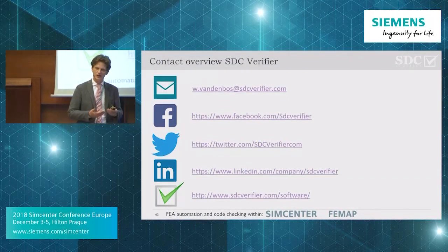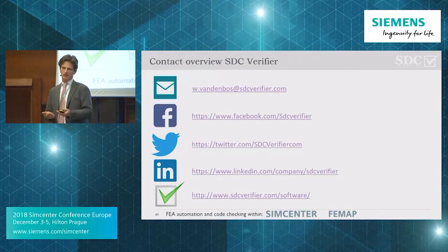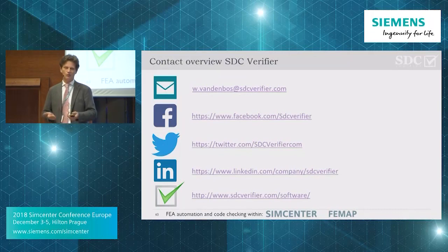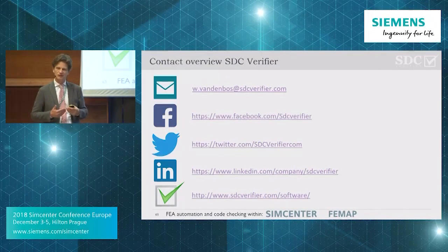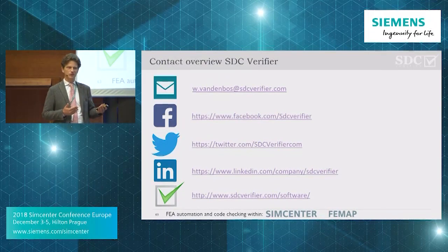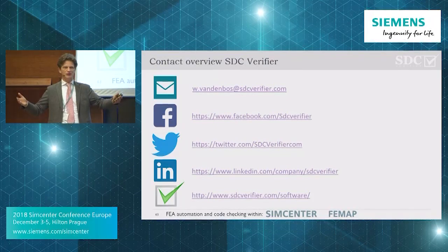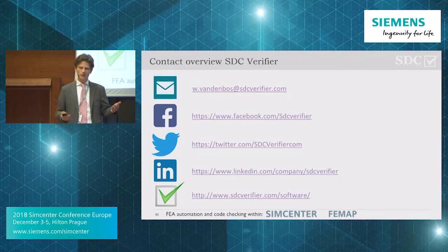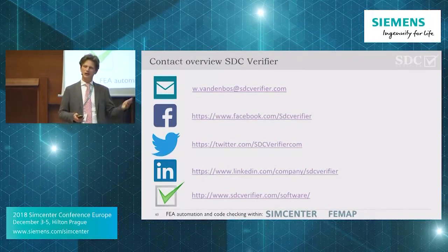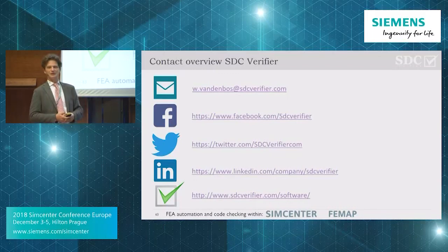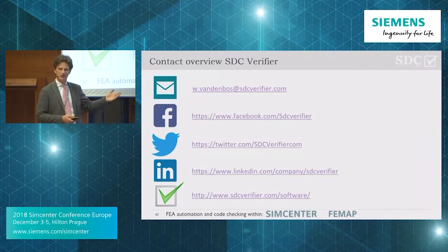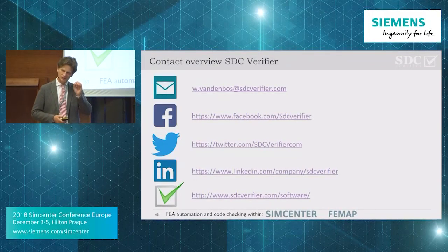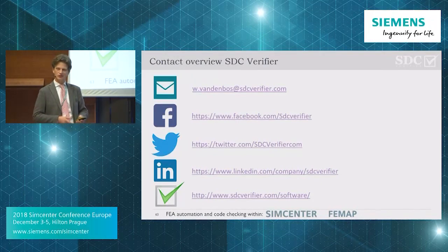So calculating according to the method of standards also makes checking what is okay and what is not okay much easier. Because if you have a lot of loads together, you check maybe the 3 biggest influences, and if the total sum of forces matches more or less your hand calculation, you think, well, it's probably okay. In this way, you can do that even for the small loads. You can say, okay, this is exactly what I need or not.